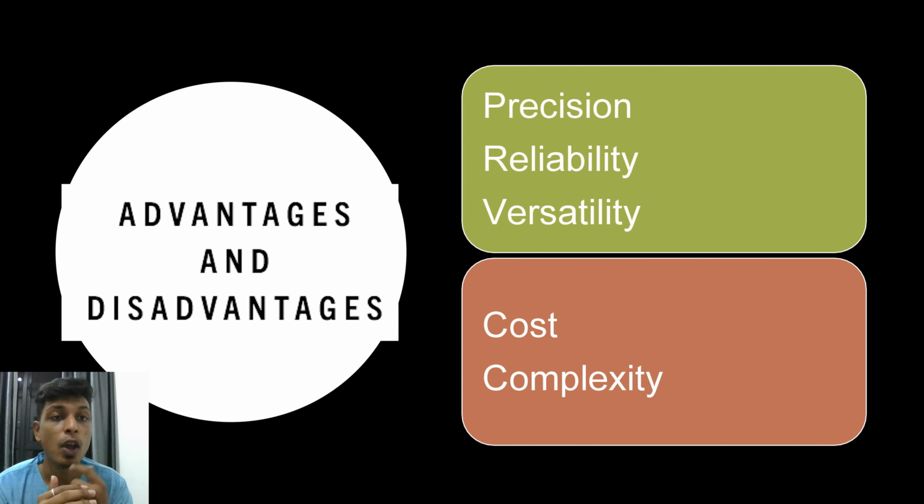First, precision. Optical rotary encoders are highly precise due to their ability to achieve high resolutions, often up to several thousand pulses per revolution. This allows extremely accurate measurements of angular position and rotary speed. Their design minimizes hysteresis, providing consistent and accurate reading without significant lag or error. The precise optical patterns and advanced optoelectronic sensors ensure minimal measurement errors, making them ideal for applications requiring high precision.